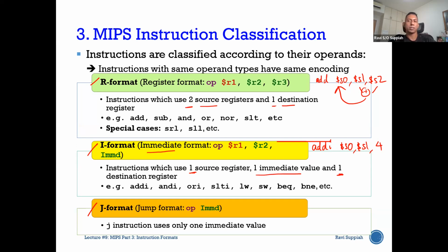In this type of instruction, what is happening is I'm specifying registers and 1 immediate value. Immediate value basically means a constant value. I want to do a particular operation, in this case add, and then I store the result. Of course it is not just add, subtract, and so on. Even other instructions like load word, store word, branch are also considered immediate. They have the same format.